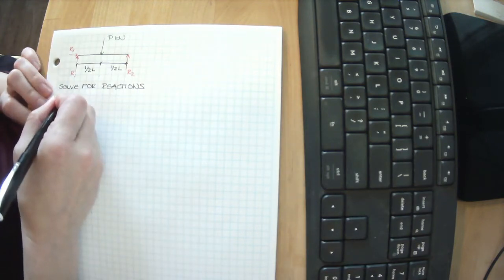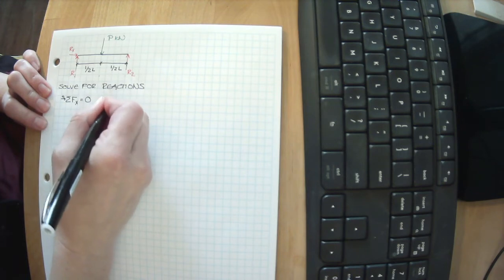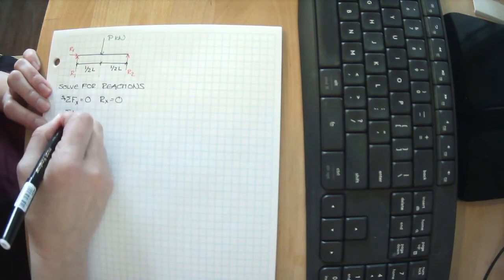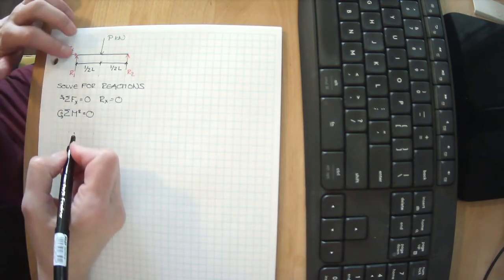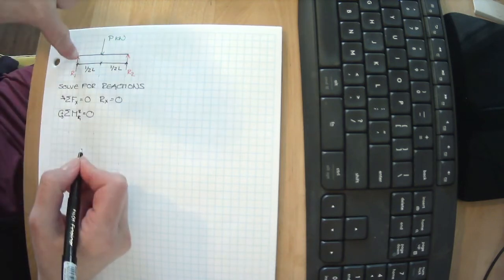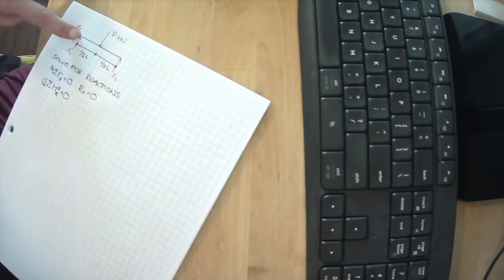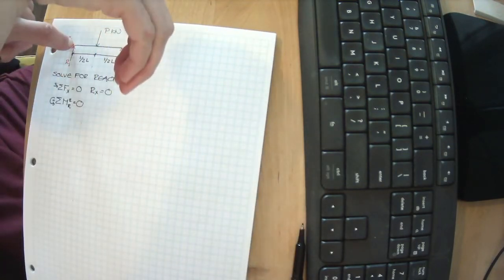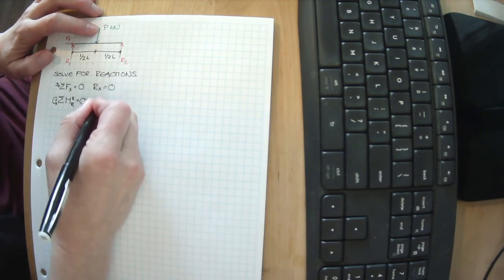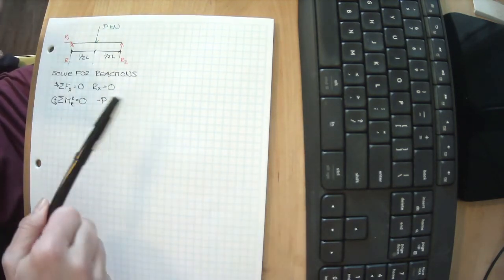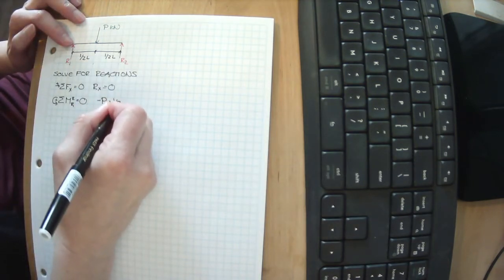All right, let's sum our forces in the x direction with everything going in that direction being positive. Rx equals 0. Let's sum our moments about the z-axis. Everything going in that direction is positive. We want to know what it takes to be 0. And let's solve it by putting our thumbtack at R1. We're going to imagine this spinning about this point right here. Okay, we've got P trying to spin it in that direction. Let's curl my fingers in the direction it's trying to spin it. My thumb tells me it's trying to spin in the negative direction. All right, so we've got minus P. And remember, to be a moment, you need a force times a distance, and P is 1/2 L away from our spinning point. So times 1/2 L.